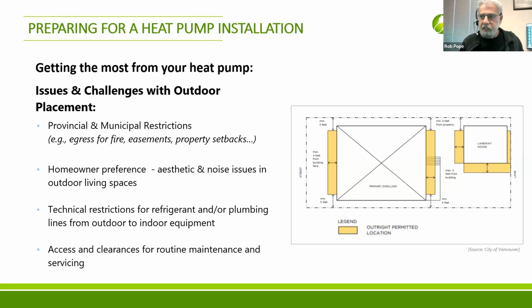Also, there are things like, how long can you run those line sets, right? Some products have a maximum limit to the length of the line set before you have to either relocate the outdoor unit or mitigate it with other technology if it's too long. I've got a line set question on that. Sure.